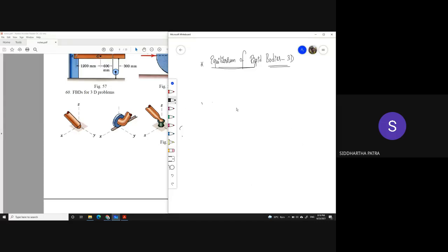Okay, so you have this thing moving on a channel. Although it is not mentioned, you'll have to assume that the wheel can never leave the channel. Now, obviously, to the rigid body, there is a support going in the z direction, RZ. But you see, this rigid body can now move along the x-axis freely. So there would be no reaction force along the x-axis.